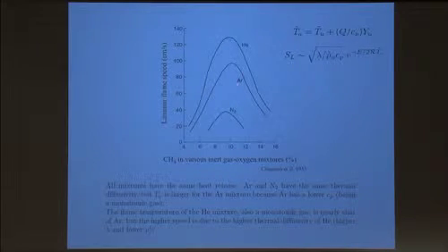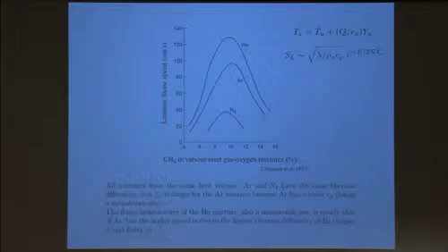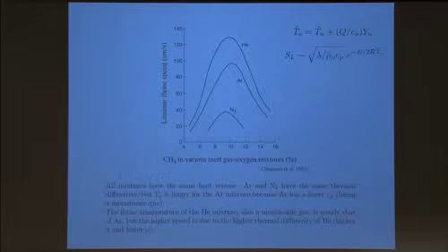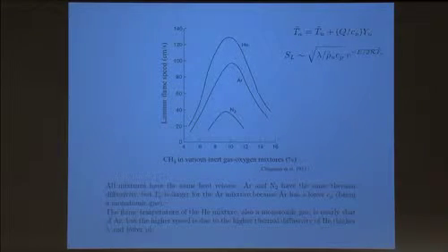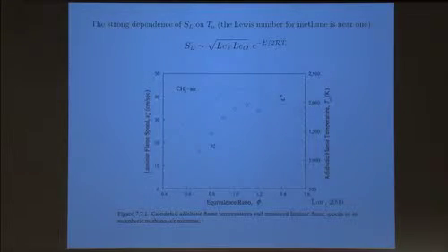Now, the flame temperature of methane in helium is nearly that of argon. However, it still has a higher speed, and the higher speed is because the thermal diffusivity of helium, as a result of lambda and rho, right? The thermal diffusivity is the factor here in the square root, is higher in the case of helium, and therefore the flame speed will be larger, okay? So you see that all these effects that you see in measurement are totally compatible with the relation that we have derived. Now, I told you about the effect of Lewis number.